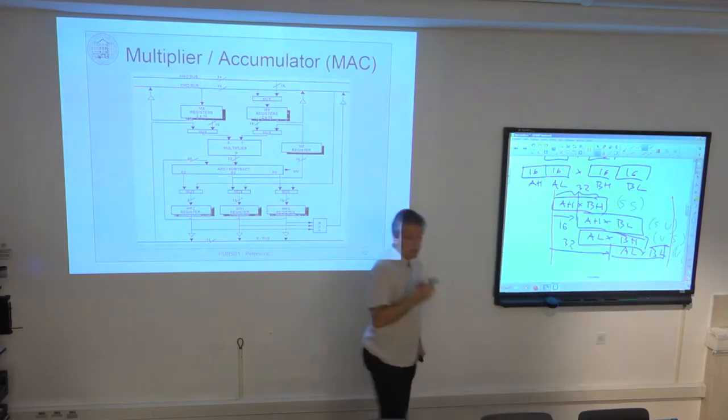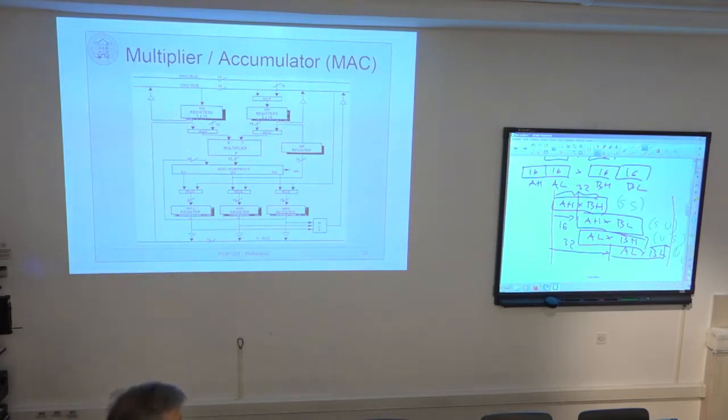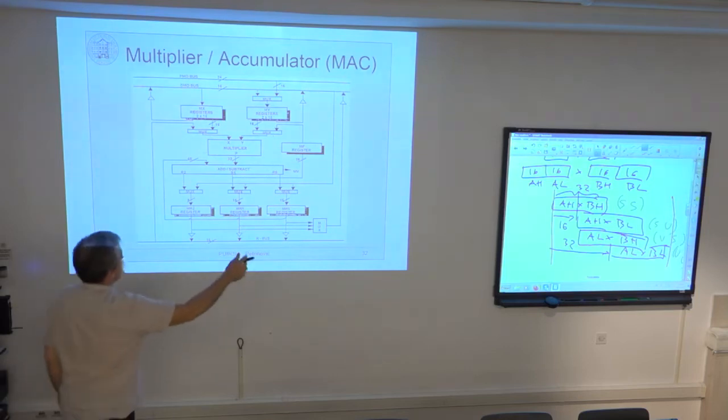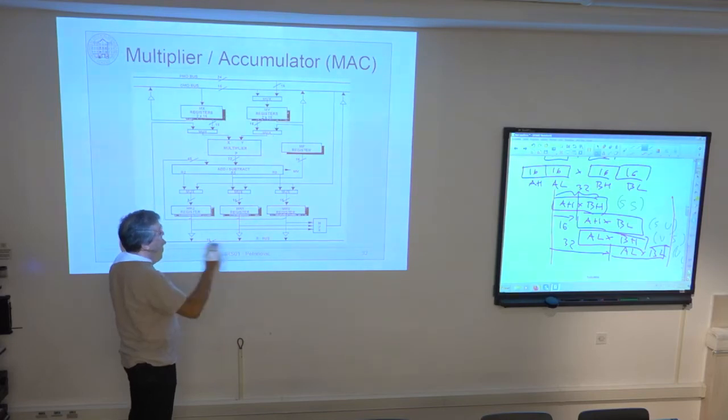And for that reason, it is necessary to be able to define the argument type for each multiply instruction as an additional flag, as an additional bit inside the instruction code. And exactly this CPU, this DSP, has 2 bits in the instruction code which are used to define the type of the argument. Okay, so this was just a discussion of why it is important to have this signed or unsigned flag for the left and right side argument.